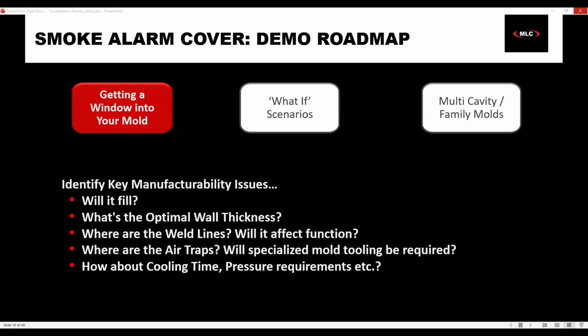If I wanted to create a mesh from scratch, there's a couple things you can do. You can actually come in here and increase the mesh size. There's also mesh controls. You can do a curvature-based mesh if something is more cylindrical or has a lot of curve to it. So there are some options. You can still come in and really have a lot of control over the mesh. What we're using here is a shell mesh. There is also a solid mesh option that is available as well. So again, I already ran everything, so let's take a look at some of the results that we get from this study setup.